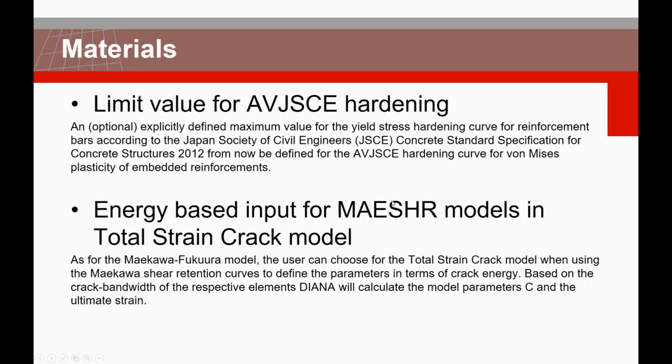Now we can control in DIANA the shear retention not only based on the ultimate strain, but also based on the energy. So that's an extra control feature that can be used in DIANA for more accurate analysis, increasing the precision of the analysis with respect to the real behavior.